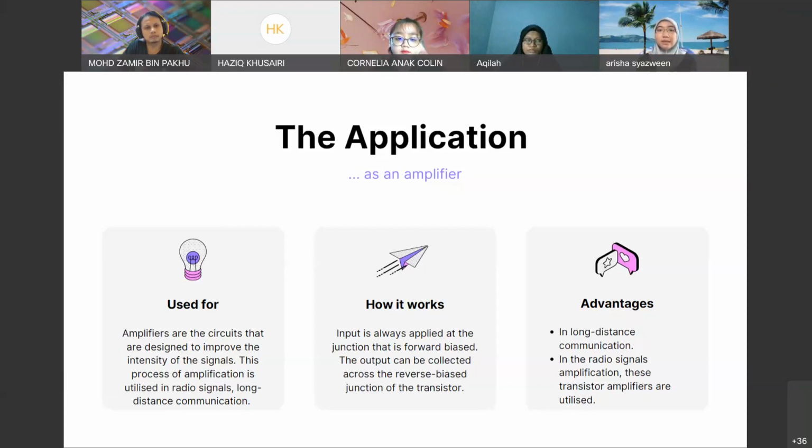Overall, the circuit design here acts as an amplifier. Electronic circuits generally utilize the NPN type of BJT, which is considered the most frequently used one. The common emitter configuration is chosen because of its gain capacity. The input side consists of resistors connected in such a way that they form a potential divider circuit. This kind of bias is most frequently used in amplifiers designed with BJTs.